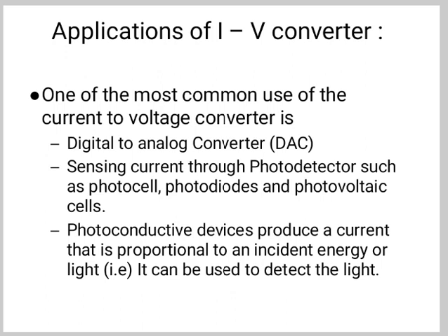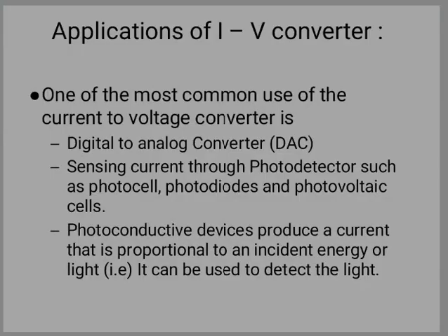Like a resistor, a transimpedance amplifier converts the current to voltage, but unlike a resistor, it has low input impedance and low output impedance even with very high gain. The compensation capacitor is connected in parallel with the feedback resistor and it is used to ensure stability in photodiode application.